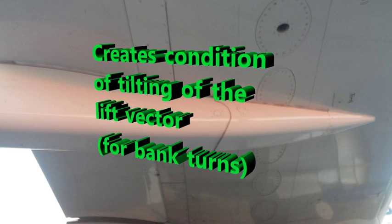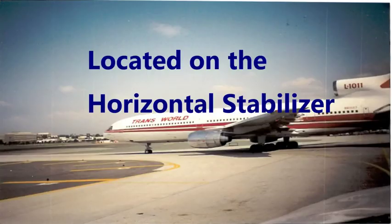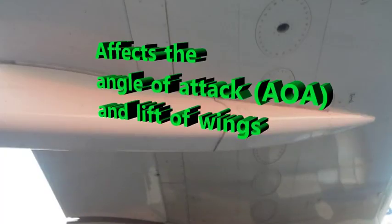Number two, you have elevators. Your elevators help with pitching the airplane. Okay, that's nose up, nose down. These are located on the horizontal stabilizer at the rear of the plane. And again, that's controlling the pitch of the airplane, which is going to affect the angle of attack and also the lift of the wings.